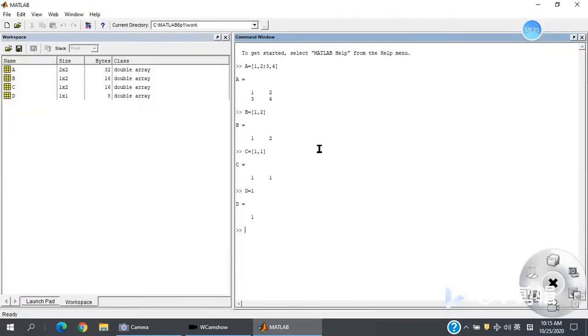Okay, then we run ACKER. Here we need A, we need B, and we need P. P will be 2 poles. One is -3 plus 3j, and the other is -3 minus 3 times j.